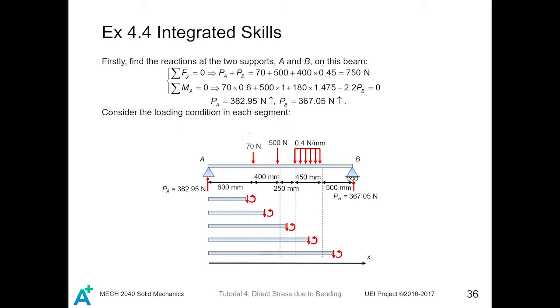Since we have concentrated loads and a distributed load, we try to divide the beam into different segments such that we can analyze the load condition in each. Because at different positions X, sometimes some forces are removed. Sometimes you have to neglect some forces from your analysis.